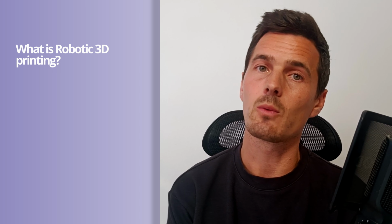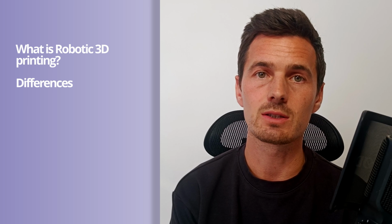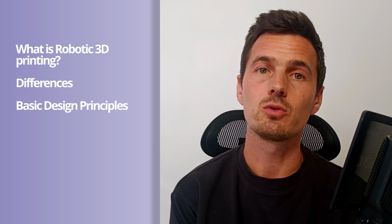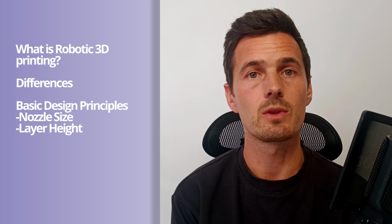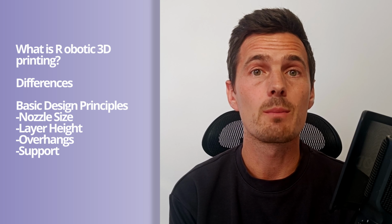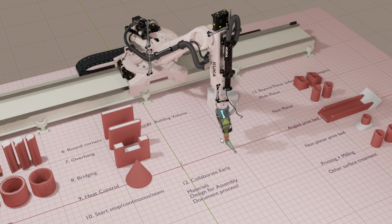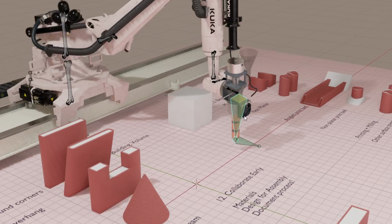We will start with what is robotic 3D printing, like what is the difference between a gantry system and a robotic arm, and how does this translate to your design. Then we will get into the basic design principles. So think about the nozzle size, the layer heights, overhangs, support, and basic failures. We will do this by showing some videos, and I built a comprehensive Blender model in which you can tweak certain settings and see what happens to your print. And I will also use it to explain these design principles.